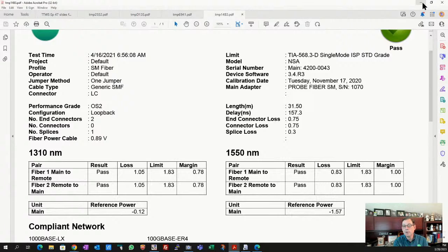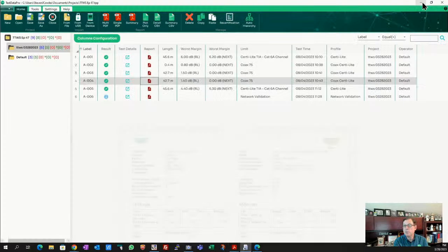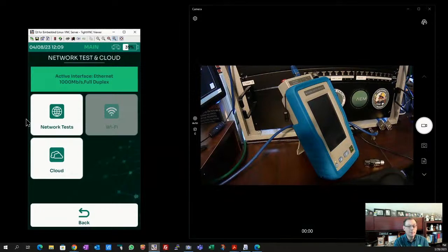And if anything ever comes up and there's a problem, you come back and run a new test, you can actually see if there's changes in the cable, and you can use the TDR tracing capability to pinpoint where that is and say, yeah, maybe this isn't so good. Somebody cut it and spliced it, put a wire nut on a piece of Cat5e. It's not a joke. We've actually seen that in the field.